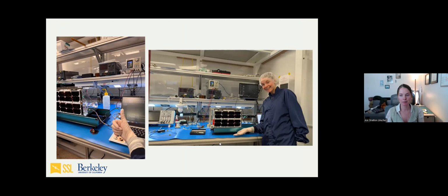And then here was my final step on the project. At approximately 4 a.m., because all of our colleagues are in Bulgaria, I had to march up to the lab. I had to get on a Zoom call, and I had 5 minutes to pull a really important red tag out of the system, change some settings, and then turn it off. The reason being, when you pack up a spacecraft, you need everything to be stowed. But when it comes out, it needs to deploy on its own. It needs to deploy autonomously whenever it turns on. But we didn't want that in the lab, right? So you have a special setting and some special hardware that keeps that from happening. But you have to disable that before launch.